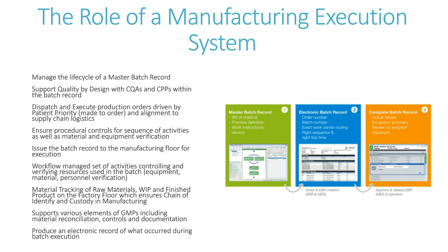In addition to that, in this era of quality by design, the critical quality attributes and the critical process parameters are also important to be supported in the batch record. So much of those measurements, whether they be done at level 1, as I indicated in the previous slide, or within the laboratory, those pieces of information are relevant to be placed into the batch record.